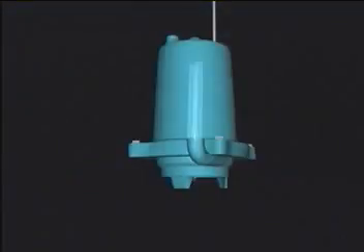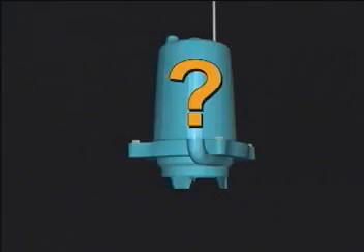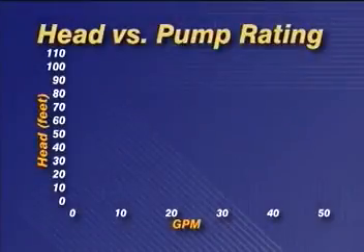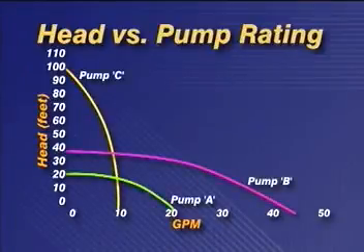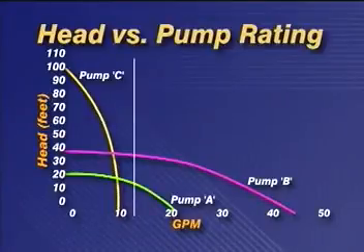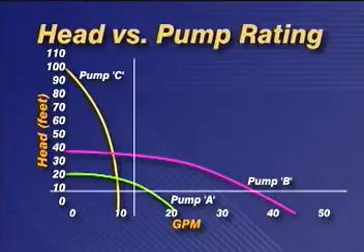Now that we know what the pump must be able to do, how do we go about matching a pump to the job? The selection itself is simply a matter of finding a pump with the performance characteristics the job requires. Your pump manufacturer has performance curves available for each model and type. On the performance curve, plot the requirement of the application in terms of pumping rate required at the calculated total dynamic head, reading across the bottom scale of gallons per minute and up the left-hand scale to the feet of head.